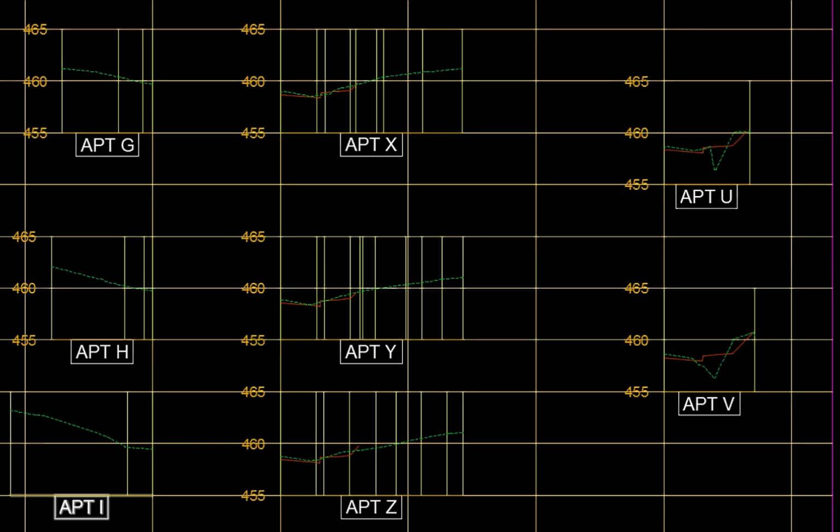The top surface profiles provide finished surface elevations at selected locations along the profile. Profiles X, Y, and Z are used to define the design finished surface profile within the roadway up to the back of the concrete sidewalk. The gutter flow line is to be moved horizontally an additional 1.5 feet toward the sidewalk. Profiles U and V are used to determine the design top of curb elevation for the new inlets to be constructed along the F alignment.